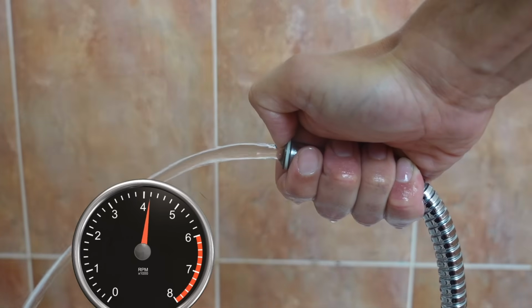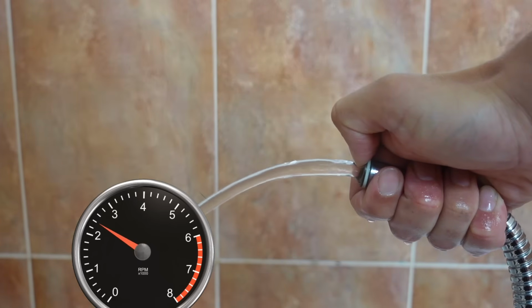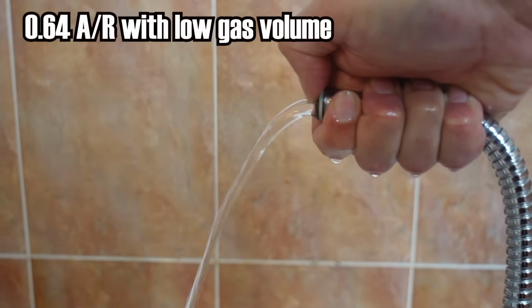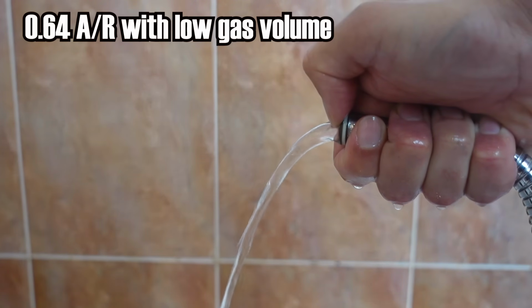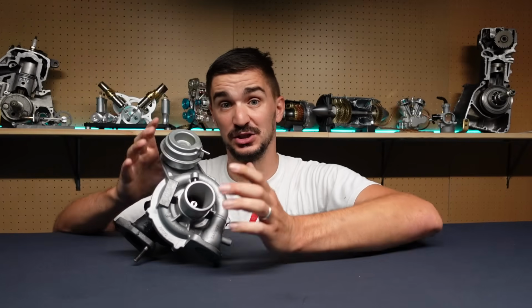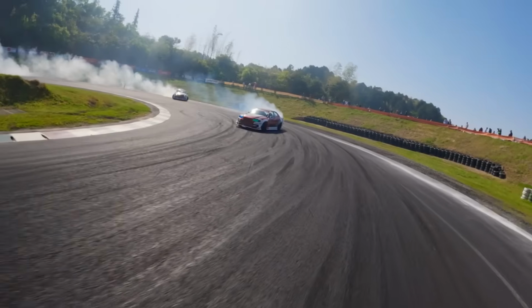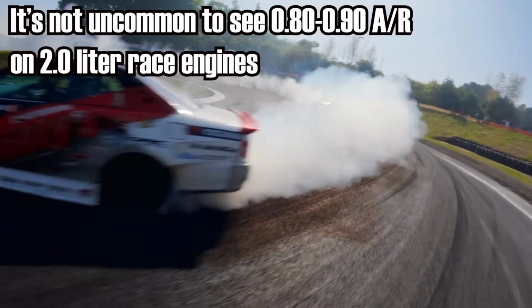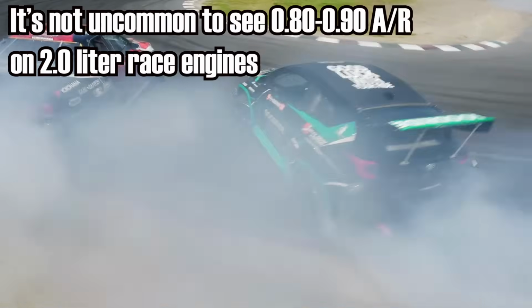However, a greater opening cross section always reduces gas velocity, which means that at low RPM, when we have small gas volumes, we are going to have less responsiveness and a more lethargic engine and reduced turbo spool. And this is why typically stock and street-oriented applications are going to have smaller A over R numbers, because for them, low RPM performance, transient response is very important, but racing engines are typically going to have larger A over R numbers because for them, low RPM performance isn't that important because they spend most of their time at high RPM.